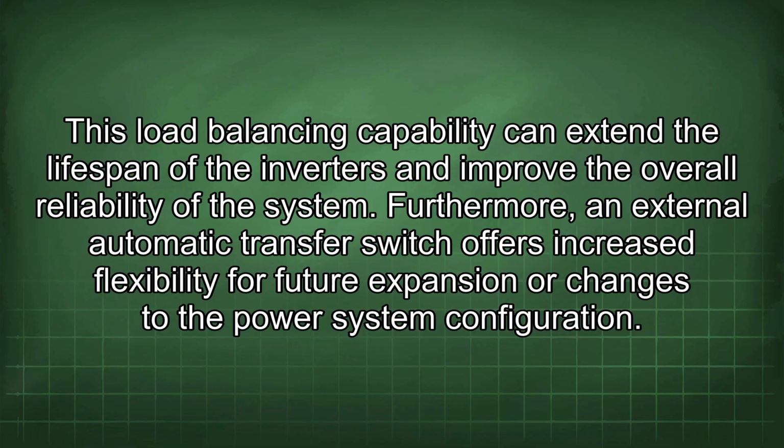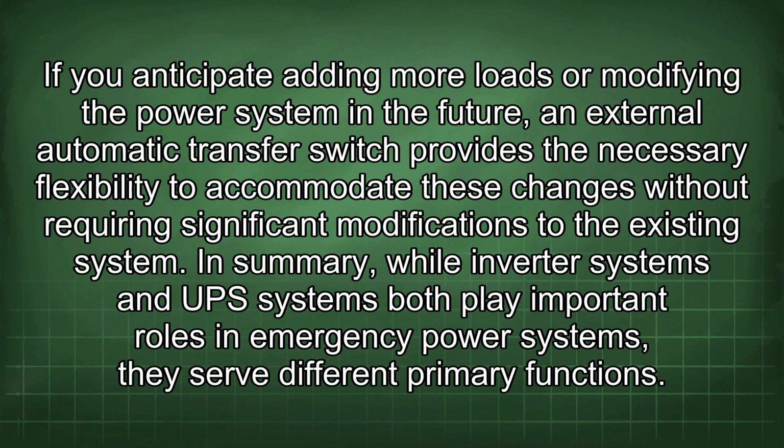Furthermore, an external automatic transfer switch offers increased flexibility for future expansion or changes to the power system configuration. If you anticipate adding more loads or modifying the power system in the future, an external automatic transfer switch provides the necessary flexibility to accommodate these changes without requiring significant modifications to the existing system. In summary,